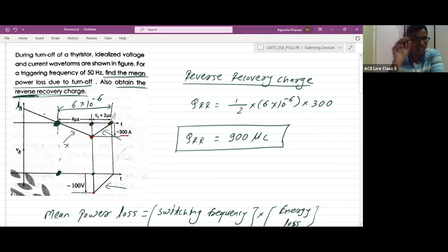It is like, suppose we have a thyristor carrying a current of 50 ampere. If I want to turn off that thyristor, suppose I have maintained some reverse voltage. Then what is happening due to that reverse voltage? Our thyristor current first of all goes on decreasing. Will it directly change from plus 50 to a negative value? No. It will decrease, na? Here decreasing means your current is forward only. It is not a reverse current. So actually the removal of the charges is taking place only during this triangle, right? That is during the negative values of the current, right?